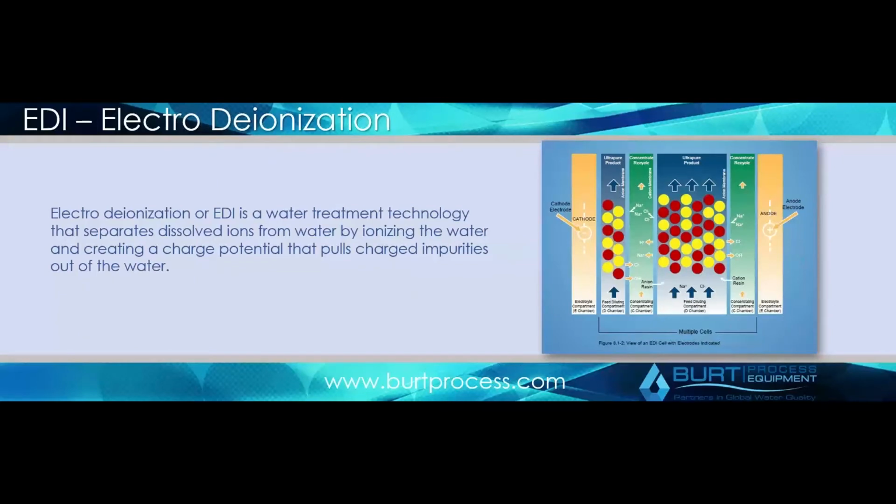One of the more semi-recent advancements in high purity water systems is electro-deionization. One of the downfalls of DI in general, or chemical deionization, having resin in the system, is it adds a consumable to the system. Obviously you're going to have to exhaust your resin. So you have multiple bottles in series. The first one exhausts, you swap it with the next one, you put a fresh resin bottle in, etc. Now you either have to exchange it or you have to use chemicals such as hydrochloric acid to regenerate it. There's a lot of issues with that.